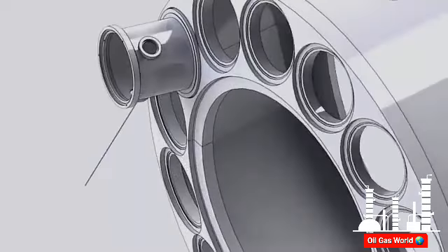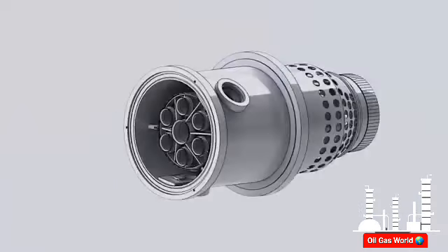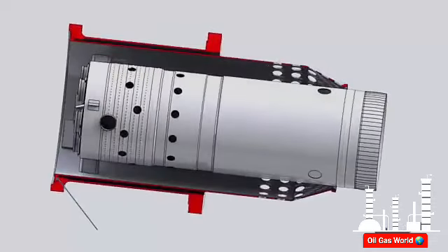The combustion chamber cover function is to carry the combustion chamber components. The flow sleeve is mounted on the combustion chamber cover. The flow sleeve forces the air to move upstream, forming a uniform air jacket around the liner for precise combustion and cooling functions among the 14 chambers.